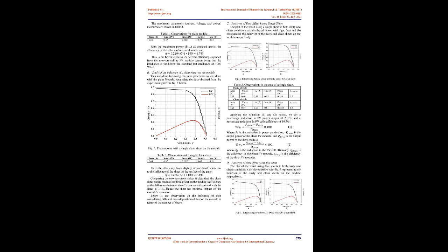Clear polyvinyl chloride, PVC, transparent papers of thickness 0.15 mm and A4 size were used to simulate the effect of dust. After having treated the sheets with alcohol to free them from oil and to enable them to better attract the soil, they were immersed one after the other and left for 10 minutes inside the solution while gently stirring it to have a homogeneous mixture in the process. The soil-coated sheets were then removed and air-dried in the lab to dehydrate. A total of 5 sheets were used to appreciate the effect of dust at different degrees of deposition.